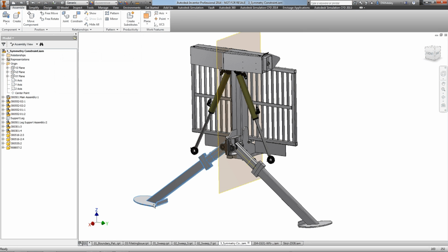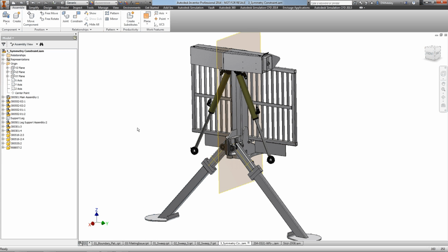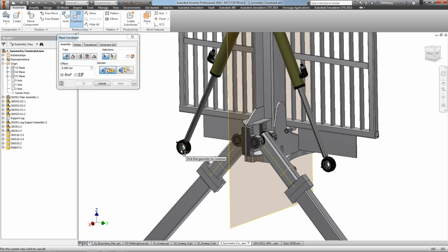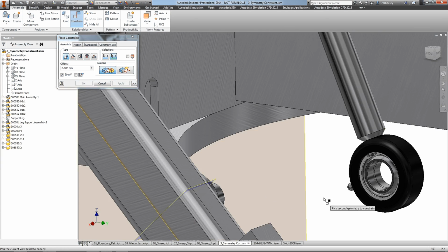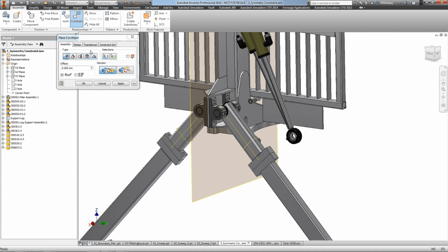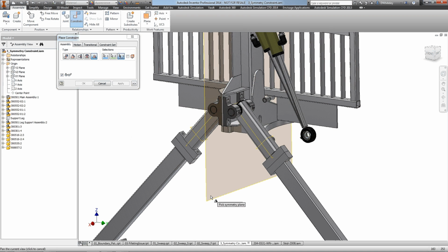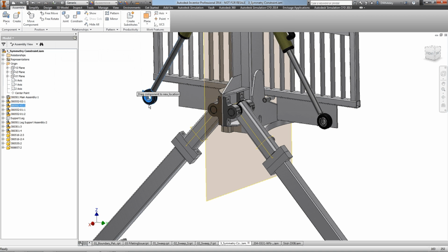That then adds symmetry to the assembly, and as you can see, if I move the component on one side, the other one moves with it because of the symmetry constraint. Likewise, if we take these actuators here, again this time I'm going to select a center of the cylinders here, not planes in this case. We can select points as well. We select, whoops, it does help if I choose symmetry and the symmetry plane, and again we've got the symmetry in action from the constraint tool.